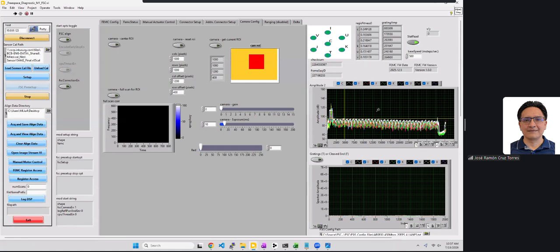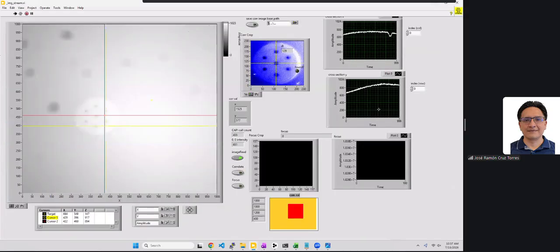Basically, you see this little black piece of tape here. That's an anti-reflective tape. Right now, as you can see from our image, we have a really strong background gradient, and part of that is just lightness, because the way this works is you have your LED on the system side, and it has to travel through a light pipe, through a gap, and then reach the end of the fiber.